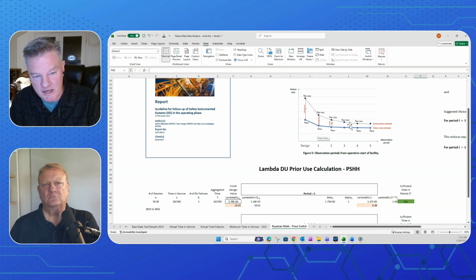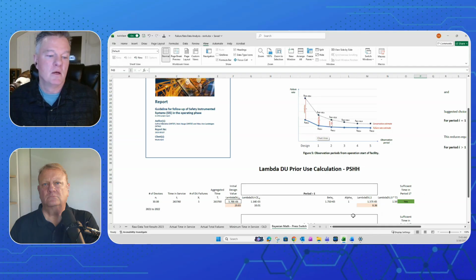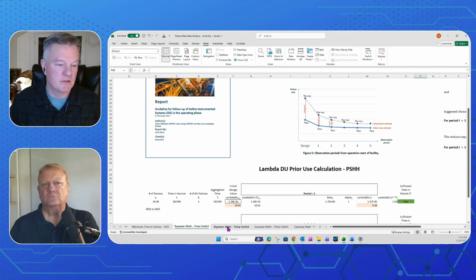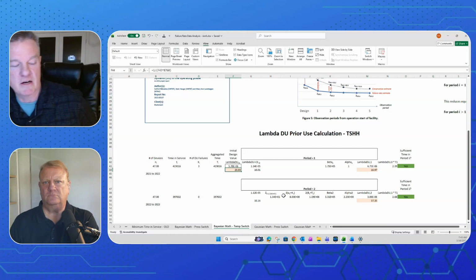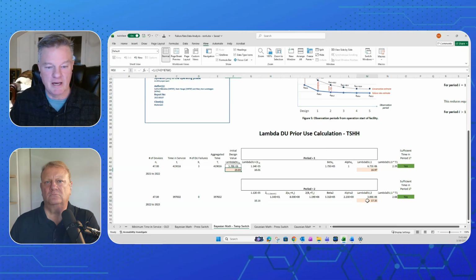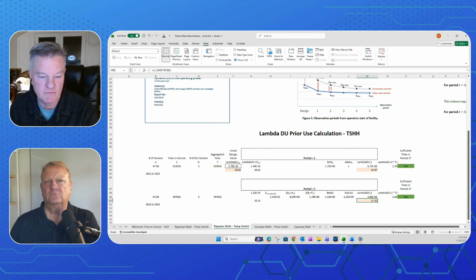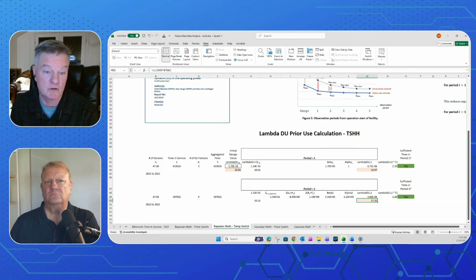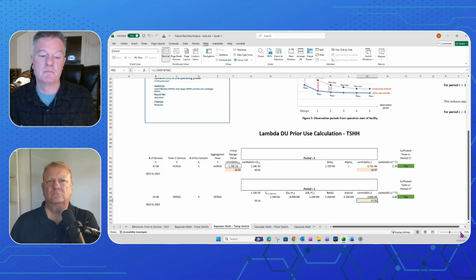And as you get more and more data, they fine tune and things start leveling out. I did the same thing for the temperature switches, and we're just gonna look at the results. We had a risk reduction factor of 20 with the assumed failure rates with a 1-year test interval. After this, we moved to a risk reduction factor of 37 with a 1-year test interval. Failure rates got better on the temperature switches. So slightly crappier on pressure, way better on temperature.